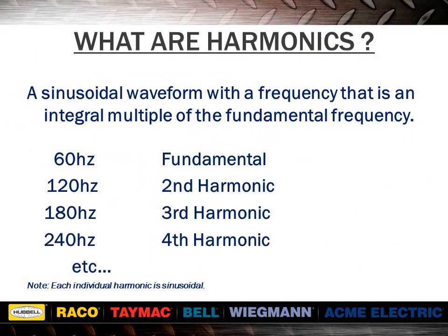Harmonics are a sinusoidal waveform with a frequency that is an integral multiple of the fundamental frequency. For instance, if 60 Hz is the fundamental frequency, then 120 Hz would be the second harmonic, 180 Hz would be the third harmonic, and so forth.